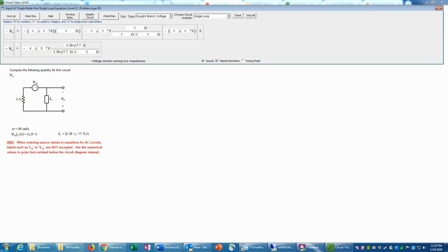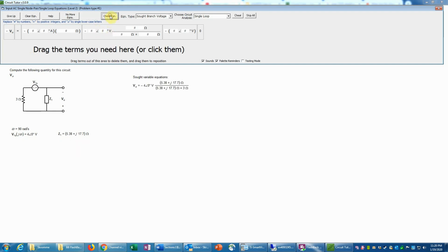So I could either put a negative sign there, or I could change the 0 to 180 degree phase angle, because remember, 180 degree phase shift is equivalent to multiplying a complex number by -1, since -1 in polar form is simply one angle 180 degrees, which you can see if you look at the Argand diagram as indicated in the tutorial. I don't want to do both of those things, of course. That would then not make any change. So I'll just put the negative sign there. Let's check that equation. So that is correct.